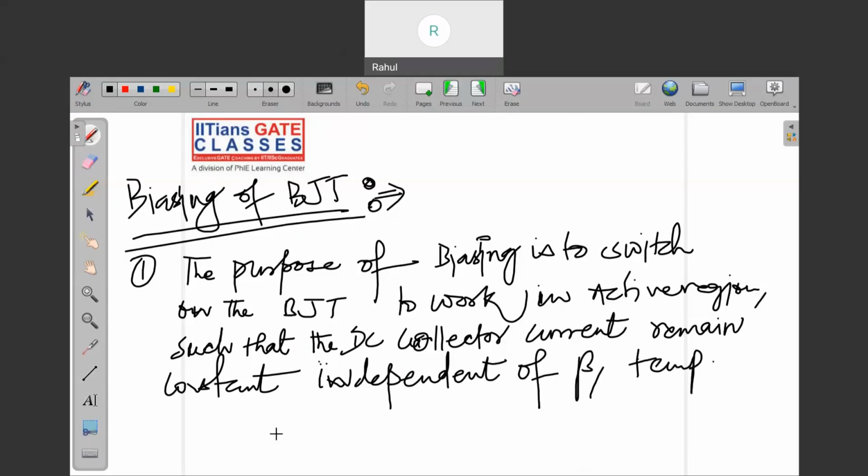IC can change because of temperature as well, because if the temperature changes, the potential across the base to emitter junction, VBE, changes. That problem is also known as the drift problem in a bipolar junction transistor. Nowadays in the GATE examination you might have seen that no questions are asked from bipolar junction transistors, because the bad parameter beta makes the transistor very bad.